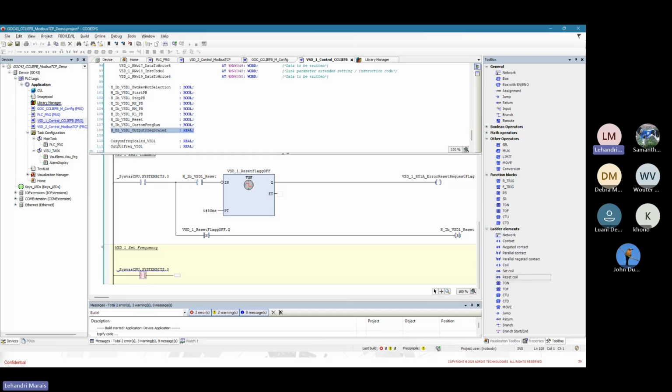And the register I'm using on my HMI side is this one, which is set up as a real to allow the user to do the decimals. So I will be required to 1, multiply by 100, and 2, convert from real to word, because the link IO is of type word. So starting off with the multiplication or the scaling.